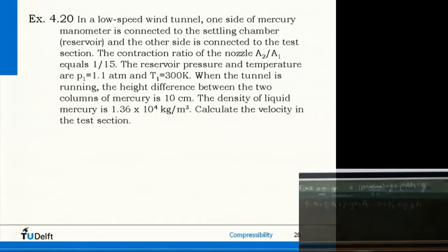So what does a manometer actually tell you? It tells you something about pressure differences, right? That's what we're typically looking for, because it's low-speed subsonic flow. Once we know pressure differences, we can transform them to velocities through Bernoulli. So this is a very handy tool, a manometer, because we know P1 minus P2 is equal to the density of our mercury or liquid times g times h.